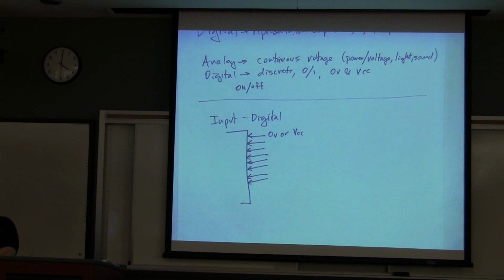10 years ago, VCC was 5 volts. 4 years ago, VCC was 3.3. More recently, it's down to 1.8. And I've heard of some chips now running at 0.9 volts. That's really low. Why would you want to lower VCC as time goes on? All right, here everybody. Say that again? Power consumption. Well, it goes beyond not only power consumption, probably one more important.